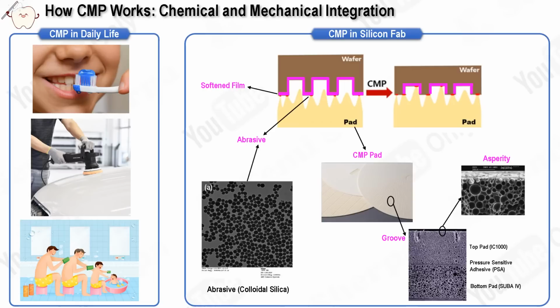In the semiconductor process, chemical mechanical polishing also uses chemical reactions and mechanical forces for material removal. The process involves a chemical reaction for surface softening followed by mechanical polishing to achieve planarization of the wafer surface by removing the deposited film with a slurry chemical.